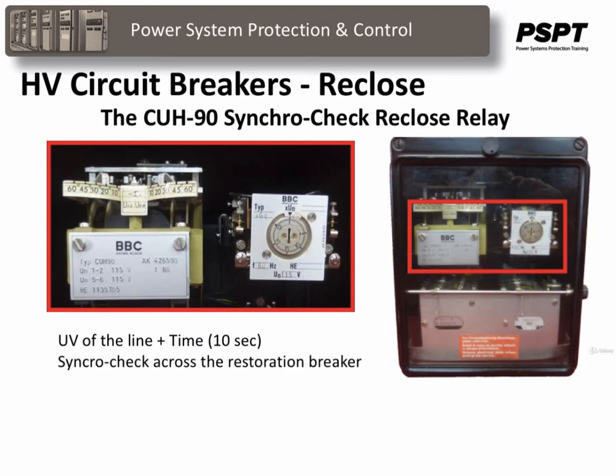Another more sophisticated way of closing the breaker is to synchrocheck across the breaker. In other words, if you've got voltage or power on both sides of the open breaker, this relay, if it is selected for synchrocheck, will actually check the synchronism across the breaker, and if all three phases are in phase on either side of the breaker, then the relay will allow the breaker to reclose.